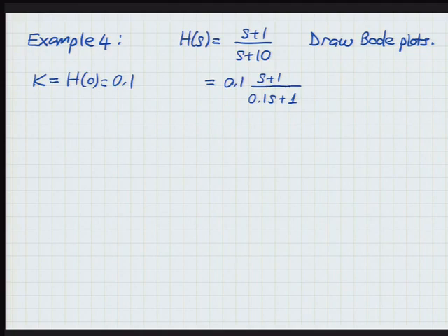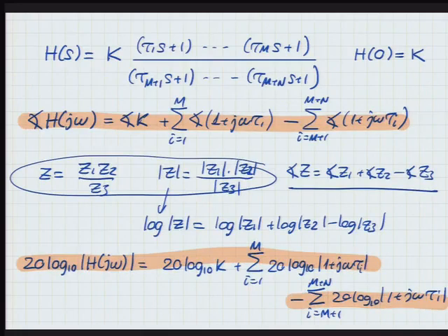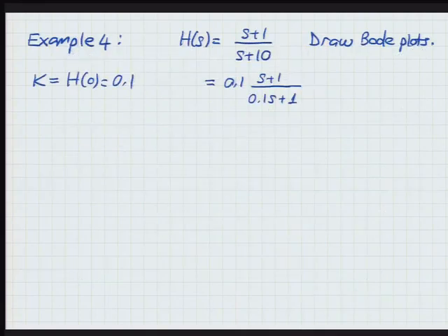Do you agree the two are the same? All right, so there's a first step where you want to bring the transfer function to this form that displays the DC gain explicitly and puts it into this tau s plus 1 form. And that's what we've accomplished here. So then the rest is making Bode plots for the gain, zero and pole, adding them up.